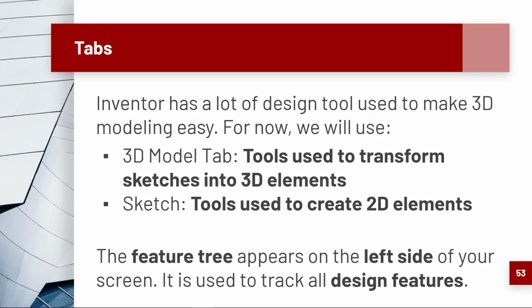Also, another thing we're going to notice on our screen is a feature tree that appears on the left side. What we need the feature tree for, and I'll point this out when I get back into Inventor, is to track all design features. So everything I make doesn't just exist. Okay, there is a kind of like a family tree. There is a history of everything that's been made in order, and you can go back and modify things as you go from your feature tree. After I see that all these notes have been updated, I'll go back in.